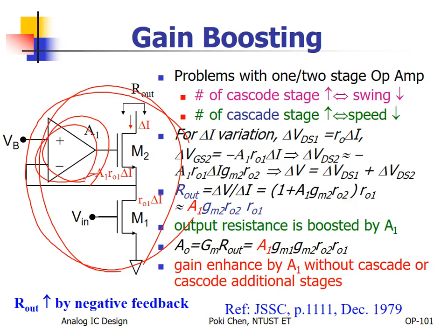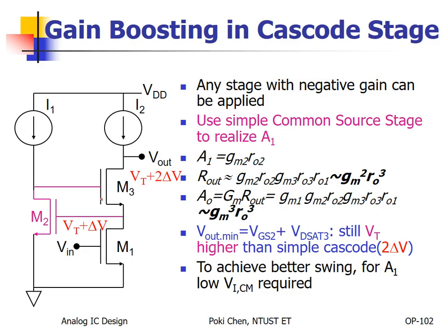But usually that is too painful: to create this op-amp, we need the help of another op-amp, and for that one, yet another. That is too complicated. If you wouldn't like to apply one op-amp for the other, then maybe this one should be good enough: a low gain amplifier for such gain boosting.